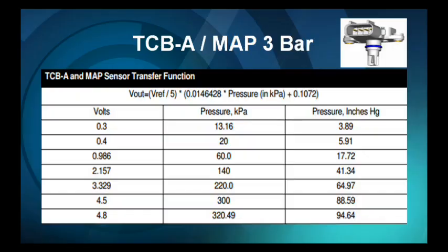Well, wait a minute. I've seen the Mustang EcoBoost in the right conditions spike up to 22 to 23 pounds of boost. In that case, we would exceed the limit of the 2-bar pressure sensor. So Ford does have, in some applications, a 3-bar or 3 atmospheric pressure sensor that could read up to 30 psi of positive boost pressure.